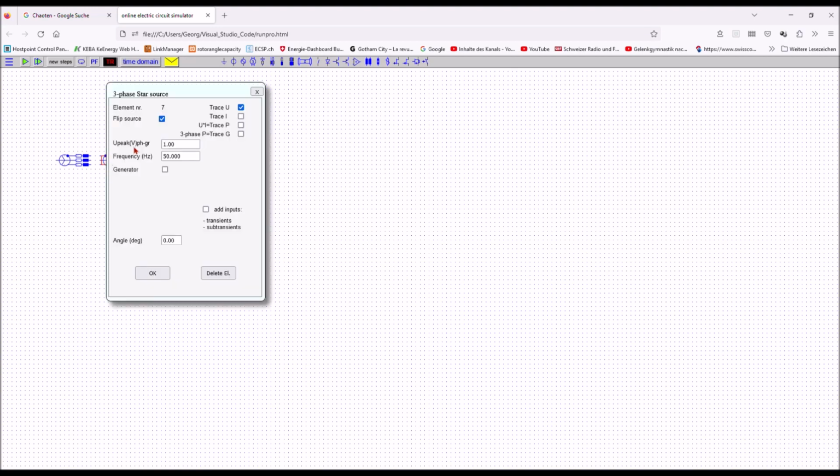So you see that if the second source would be connected like this, with the dot on the bottom, it would not be correct, therefore we have to flip the source. You can flip it either on the menu or directly on the input form on this box here. Now everything is correct, the 2 dots meet each other and I can connect the sources correctly.